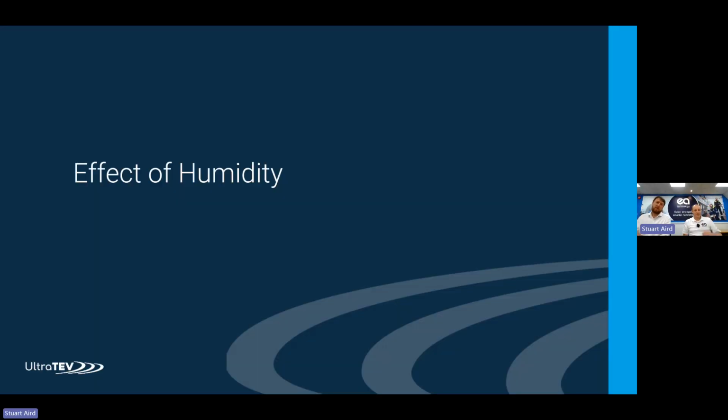Thanks, Chip. It's quite topical. Anyone in the UK, unfortunately, probably suffered the storm last week, and quite a few areas were flooded. So humidity in the substation might be a permanent thing. It might be there due to the nature of where the site's situated, etc. But it can also be a very temporary thing, something that comes through flooding, and the damage is caused. The PD starts at that point, the deterioration starts. You're happy your site's dried out, everything goes back to normal, but that deterioration continues over time. So if you have had any sites that have had flood damage, I would recommend considering that, following up on what the impact of that might be, and checking going forward.